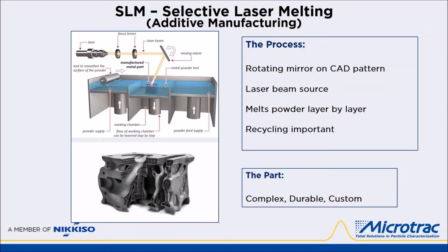Below is an example of the complexity of a metal part that can be made by laser melting. Parts can be very durable as they're made in one structural piece and they don't require any subassembly. They're also much more customizable on demand. One machine supplied with a number of different CAD programs can be used to make individual custom parts on demand. This saves the large expense of tooling to produce a single part type.